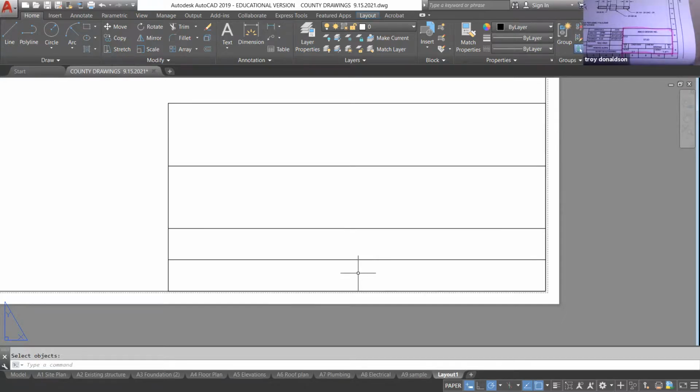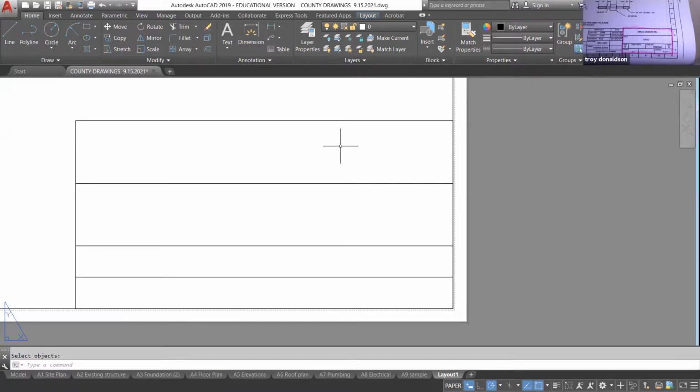And you probably can keep going here, but I want to place some text. Okay, I'm going to place the Amco Design Inc. Now, there's a few ways to do this. If you want it perfectly centered, then you need to mark that center point. So I am going to draw a line. This would be what engineers do. We like things precise and perfect. The reason I do this diagonal line is I know the midpoint is the exact geometric center.